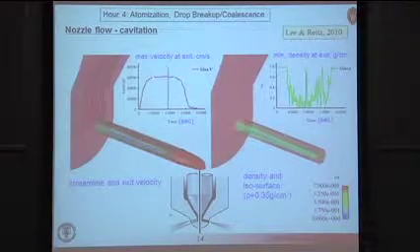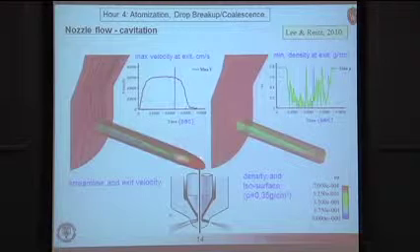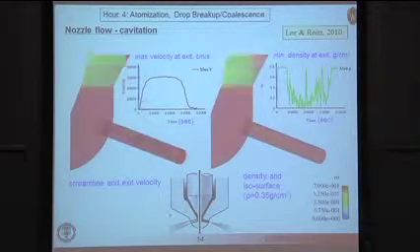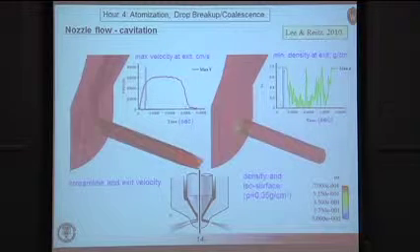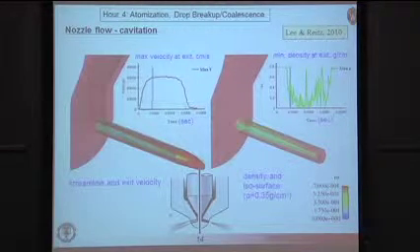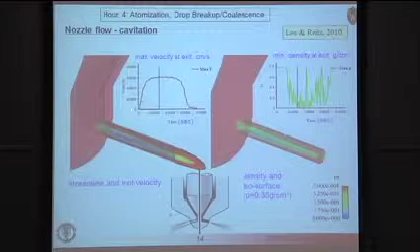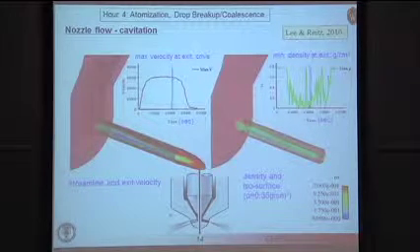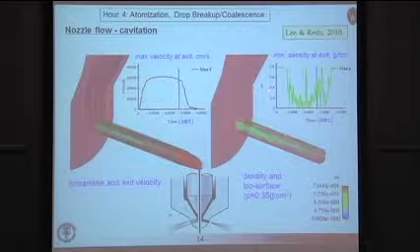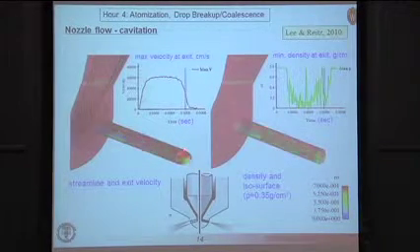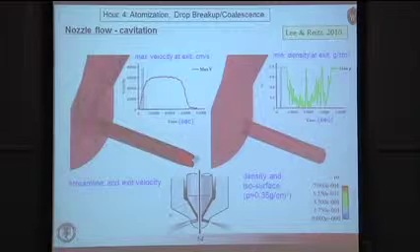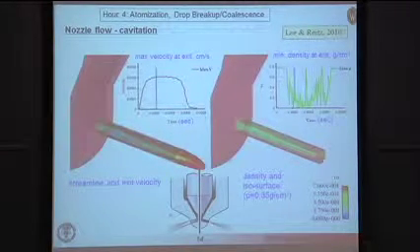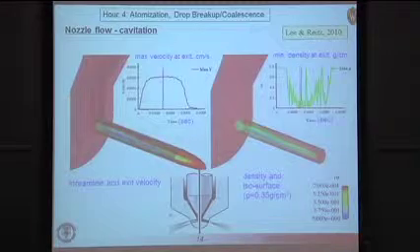Of course, the velocity rises during the startup, and then you see the falling velocity and the cavitation region going back to the nozzle. So what you get from a calculation like this is essentially the injection velocity as a function of time, and also information about the density of the fluid exiting the nozzle, which can be used to verify simpler models.